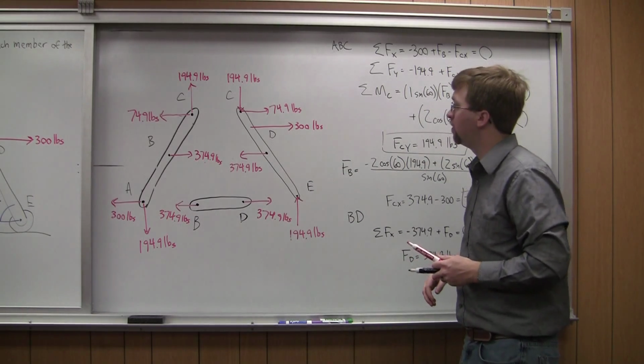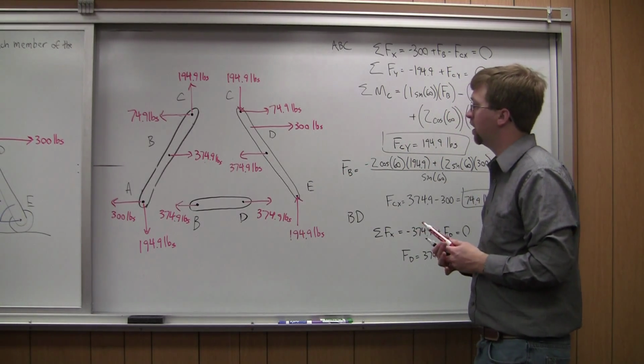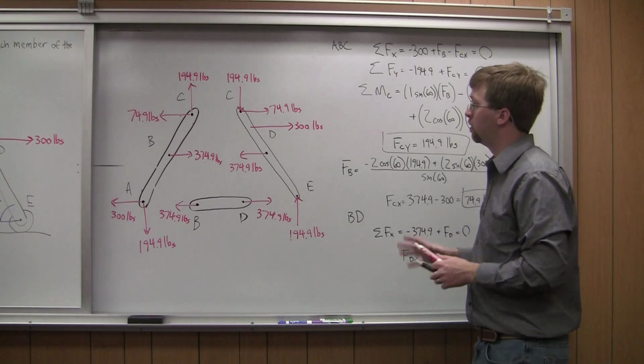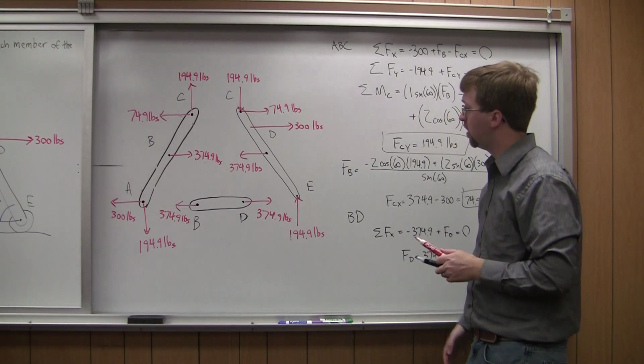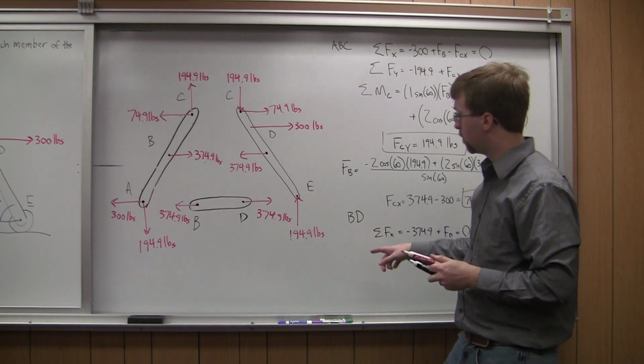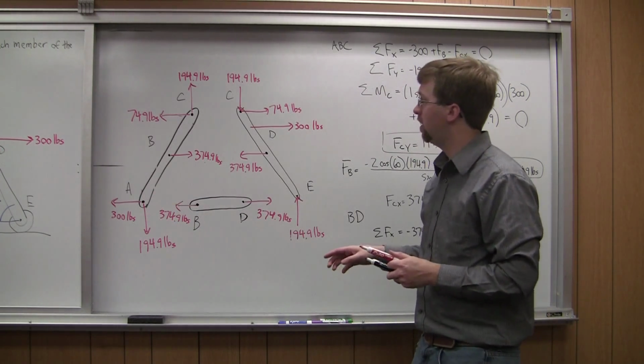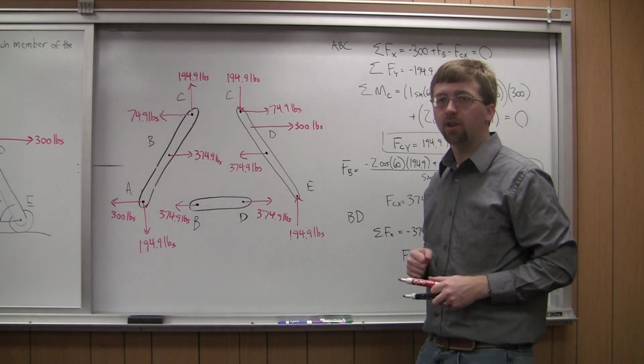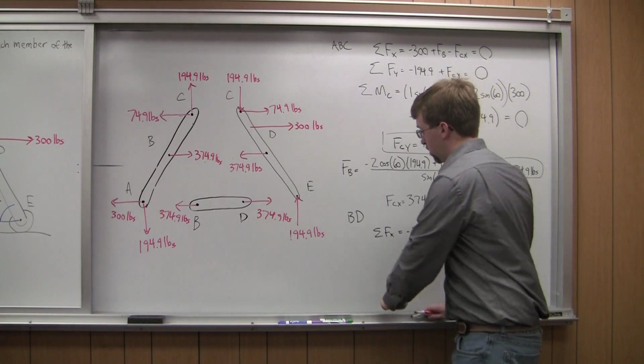And so with that, we've solved for all of the forces acting on our members. So we split it all up into different pieces, and I've got both the external forces down here at the base, and the forces that are internal to the whole A-frame structure. So with that, we've solved our problem.